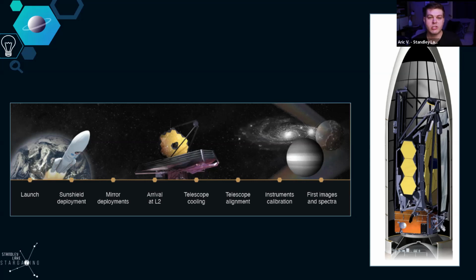You have conduction, that's when an object is touching another object, like when you pick up a cold glass of water, you feel that heat transfer from hot to cold. Then you have convection, which is like the wind blowing, and that's the wind chill effect, which we're all too familiar with. And then you have radiation transfer, and radiation is like feeling the sun's warmth come through a window.